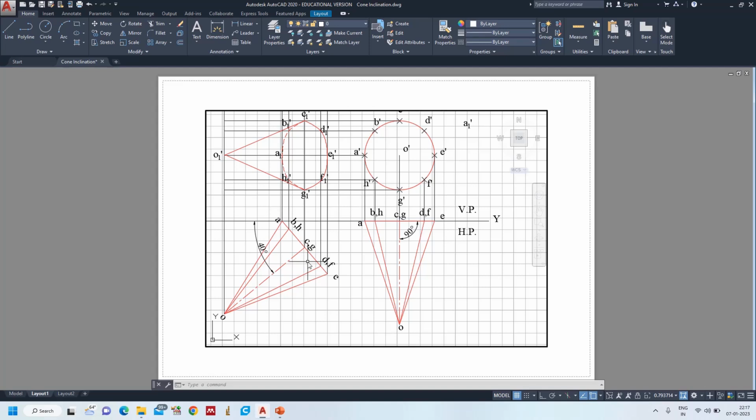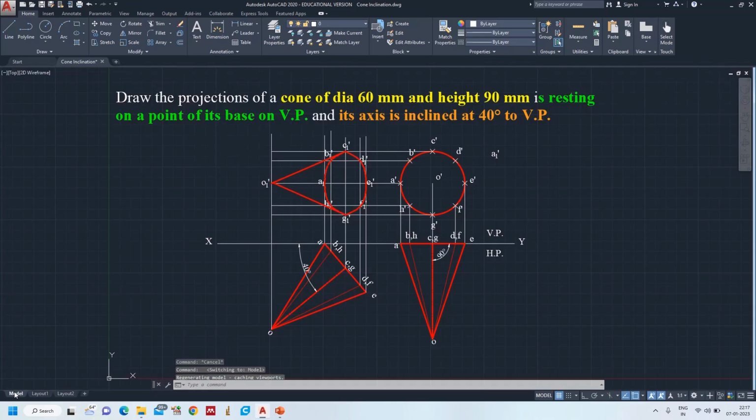So based on the system, each and every computer, each and every person, it will vary, so no need to follow the same values. You can change line type scale. Suppose previously 0.5 is right, now I am changing it to 0.4. See, again it changes. So based on your adjustability you can change the scale. The maximum value is 1, the minimum value is 0. You can keep any value in between 0 and 1. Don't go beyond 1. Okay,